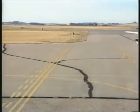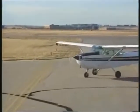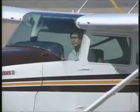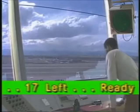Once the pre-takeoff checklist is complete and you're ready to depart, taxi up to the holding line, switch from the ground control to the tower frequency, and let the tower controller know that you are ready to take off. Be sure to give your direction of flight or destination. Sutton Tower, Cessna 62740, 17 left, ready for takeoff, VFR southeastbound.